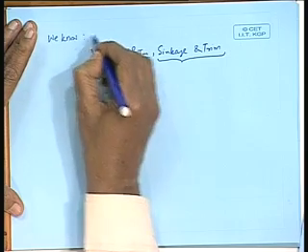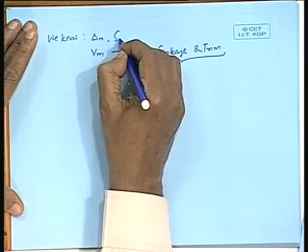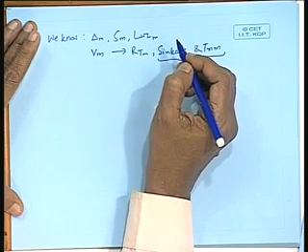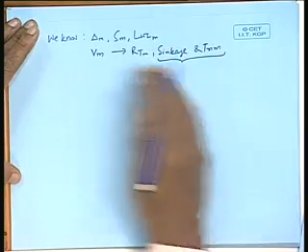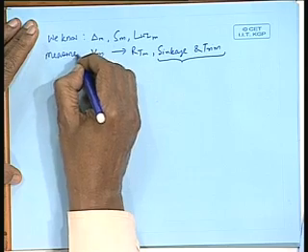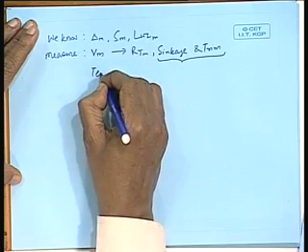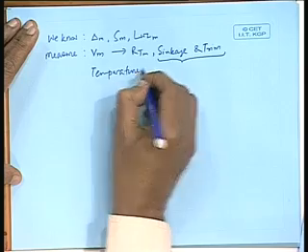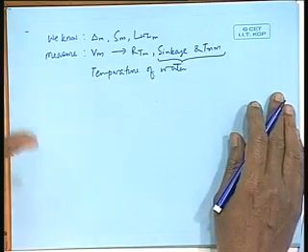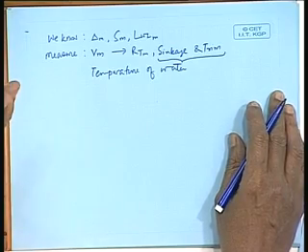We know model displacement, model wetted surface, length on waterline of the model, right, and we will see what else is required. All this is known. We also have to measure the temperature of water, because the density and kinematic coefficient, these two items that are very important for our calculation, are temperature dependent. So, we have to measure the temperature to get these values. Now, let us see